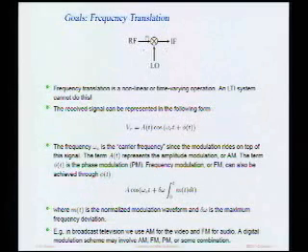We draw them as a circle with an X to emphasize the fact that they're kind of taking a product. Not strictly valid, but it's a good first-order approximation. If I take the product of two, let's say, cosines, the output is a cosine at the sum frequency and a cosine at the difference frequency. So certainly products are a way to build mixers.